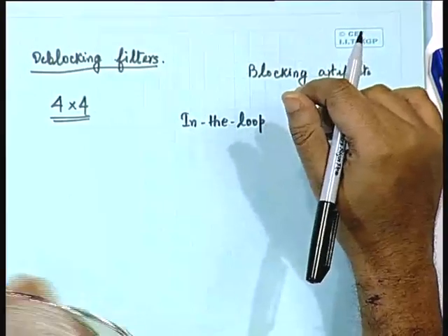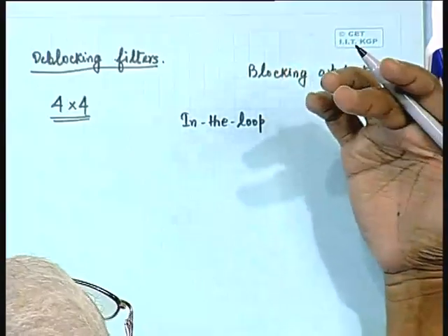What I talk of as the encoder loop, I think you understand. A few classes back when I was explaining the encoder, I showed you that the encoder has got a forward path for the propagation of the residual coefficients, and also it has got a feedback path, in order to derive ultimately the predicted signal.